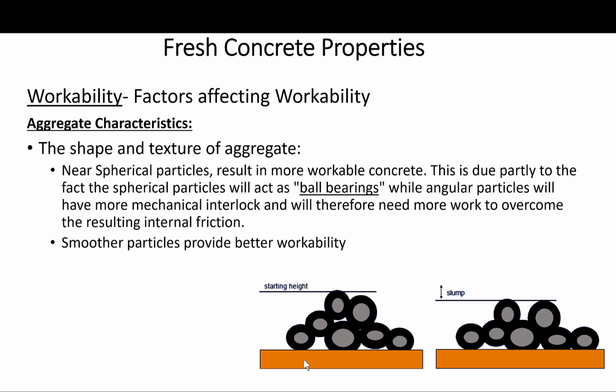Also, the porosity of the aggregates may affect workability. If the aggregate can absorb a great deal of water, that means less will be available to provide workability. So it may be necessary to distinguish between the total water content, which may include absorbed water, and the free water content, which is available to provide workability, and which determines the water cement ratio. We will talk about this concept during the mix design lectures.